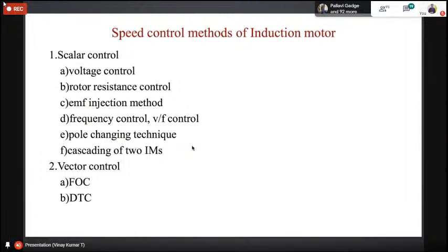We can reduce the AC motor torque equation order back to first order, right? So that is the advantage of vector control, FOC. With direct torque control also, we can improve the dynamic response of the machine very fast, similar to a DC machine, right? Implementation is very simple.